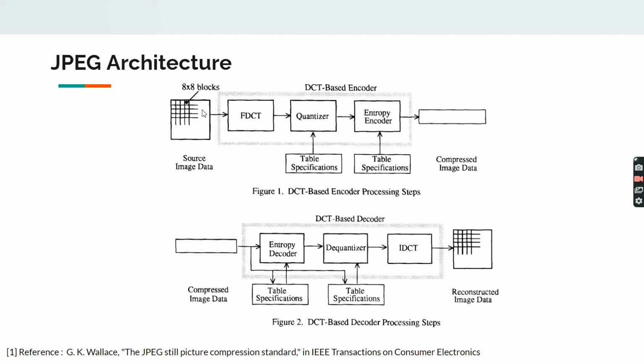Decoder IDCT. The IDCT reverses the processing step at the decoder. By summing the basis signals, it reconstructs a 64-point output picture signal from the 64 DCT coefficients which have been quantized at that point. In terms of mathematics, the DCT is a one-to-one mapping between the image and frequency domains for 64-point vectors. The DCT in theory causes no loss to the raw picture samples. It just transforms them to a domain where they can be encoded more effectively.